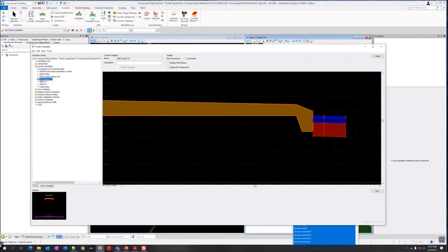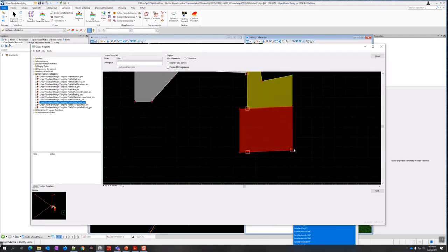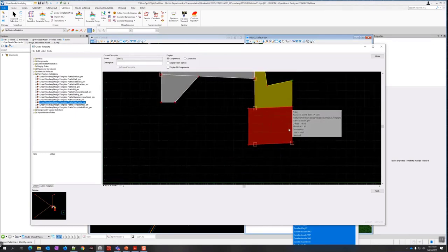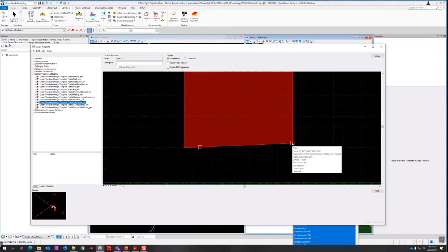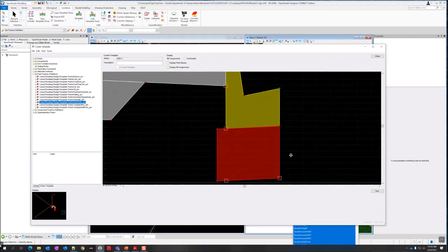So if I also check my end conditions, I can do the same thing there. Point feature definitions, subgrade PM. So this one's tricky, okay? First of all, this point here, is it going to be merged with the other one? Is it going to be right next to it? That's something to be aware of, you know, how it relates to the pavement that it's right next to. If it's right on top of it, it's probably not an issue. But just check that, and if your base depth is different and it's vertical, then you might want to make sure this has a horizontal offset.